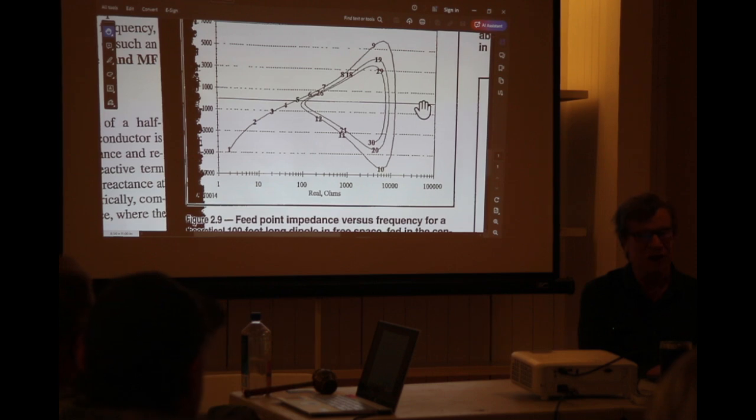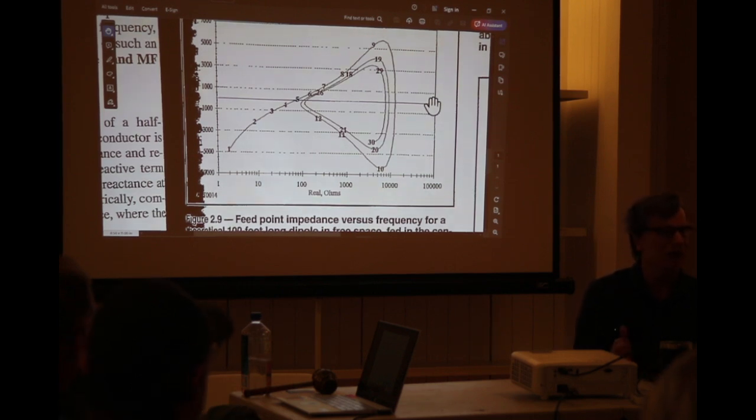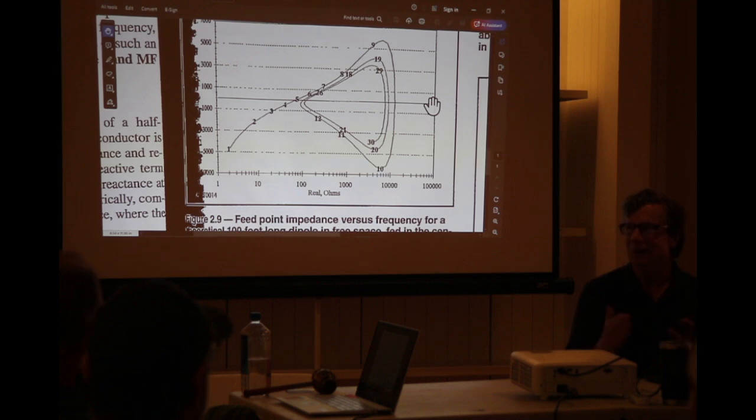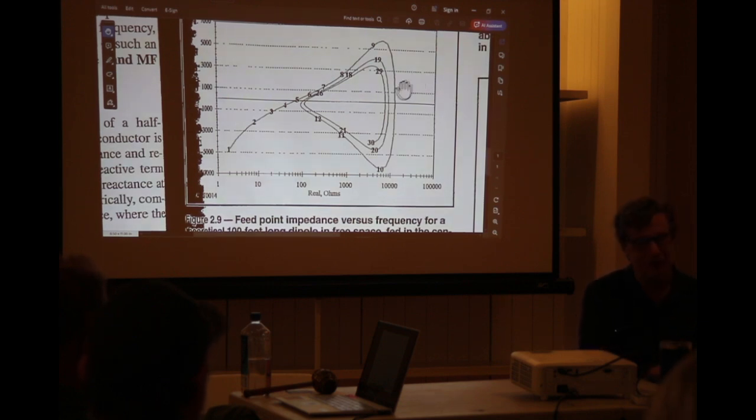wire. It doesn't mean it's not a good antenna, and the resonance or lack thereof has absolutely nothing to do with the radiation efficiency. This is one of the big misconceptions, that an antenna has to be resonant to radiate. It has nothing to do with how well it radiates. It does have something to do with how well you can feed power into things. So we want the antenna system to be resonant. Doesn't mean the antenna itself has to be resonant, but we want the system to be.